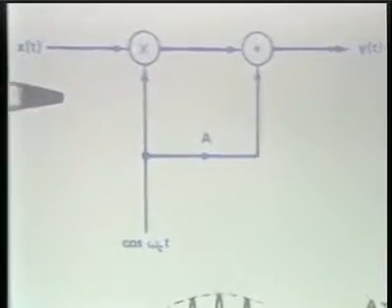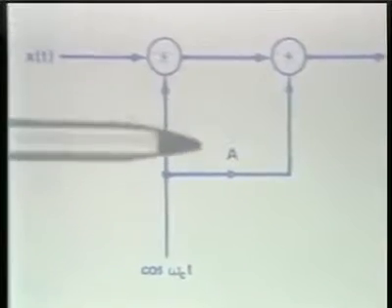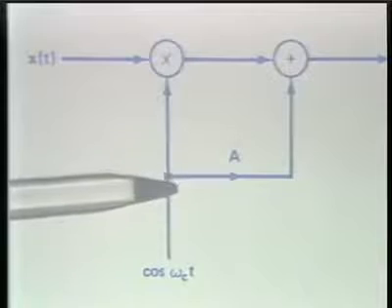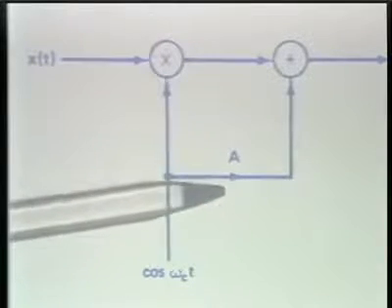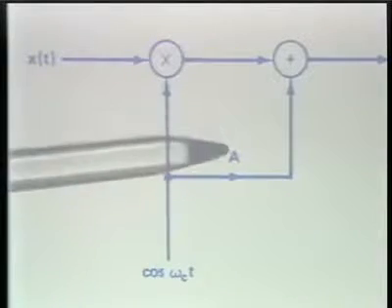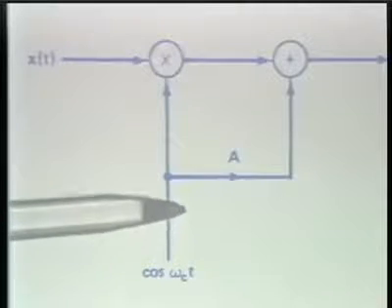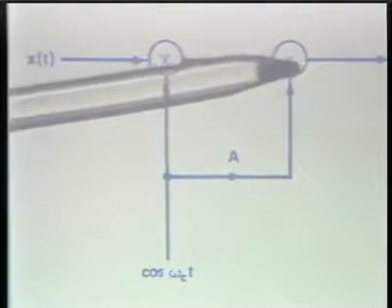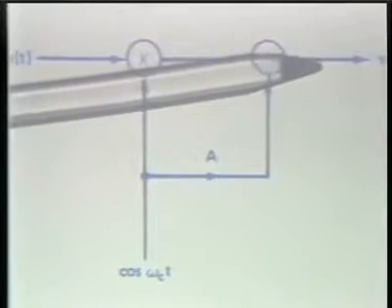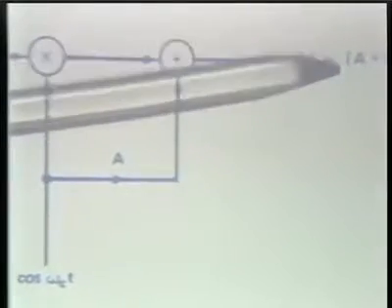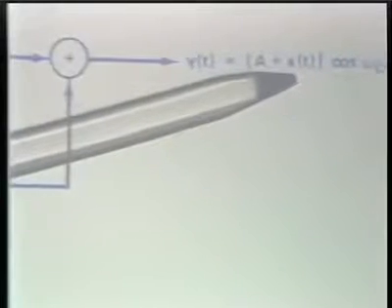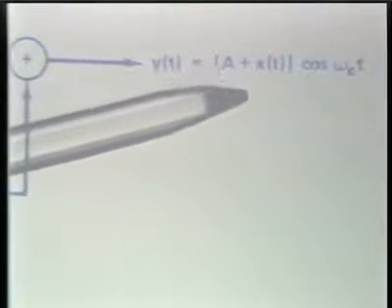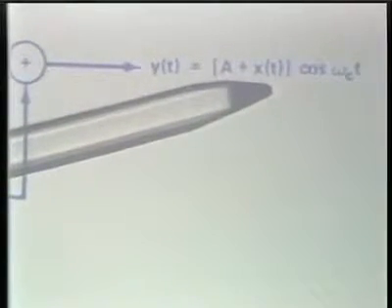And then, specifically for sinusoidal amplitude modulation, we may or may not inject some carrier signal, A times the carrier, or equivalently, if we look at the modulated output, the injection of the carrier is equivalent mathematically to simply adding a DC offset or a constant to the modulating signal.